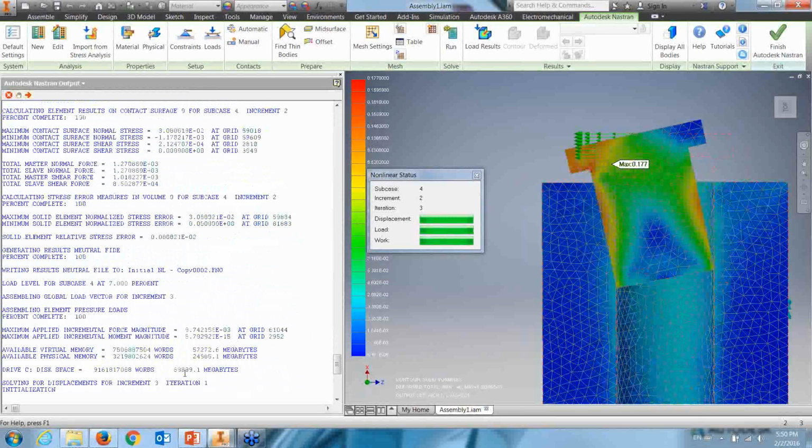It's going to be really hard to maintain that. So if you give it a very, very small amount of flexibility, it's going to prevent convergence problems. So you never want to say 0. You just want to give it a small value for allowable penetration. And in the scheme of things, 1 e to the minus 7 is pretty darn small given the scale of the model.